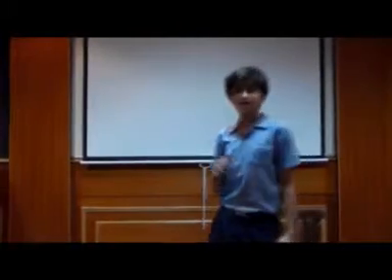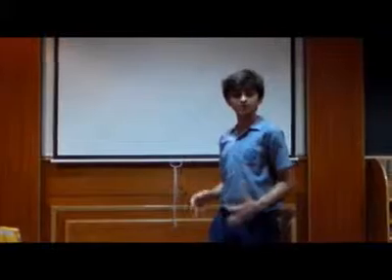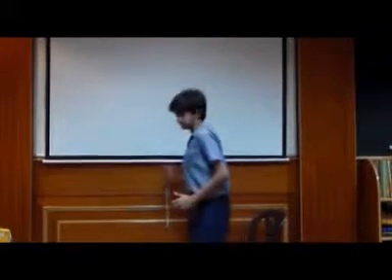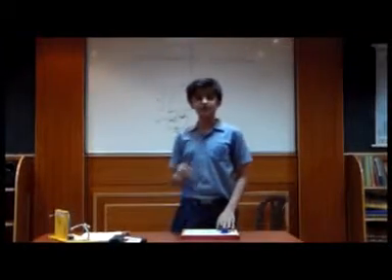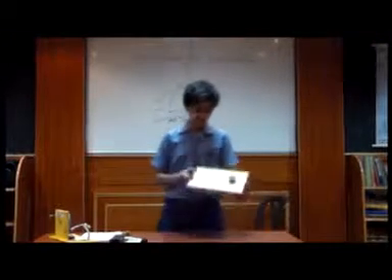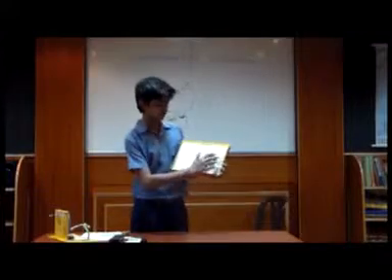Hey friends, today I'm going to explain the principle and working of an AC generator. The main question is, on what principle does an AC generator work? The principle on which the AC generator works is EMI, electromagnetic induction. To understand its working, we have two prototype working AC generators. The first one, in a fixed coil, a magnet rotates. When it rotates, as you can see, the LED glows. This is because of induced EMF in the coil.